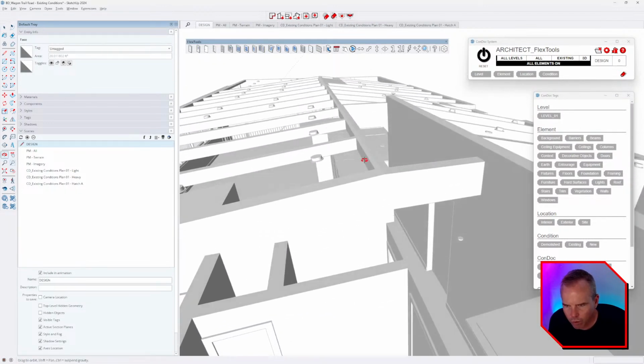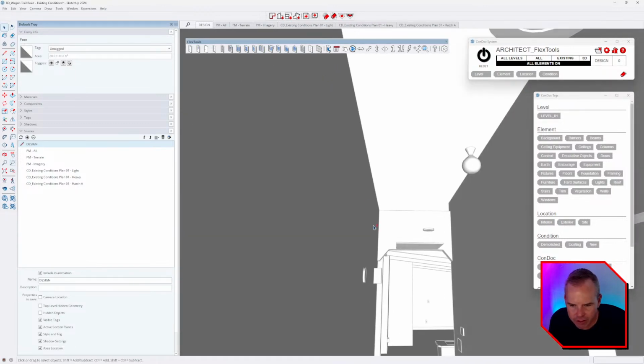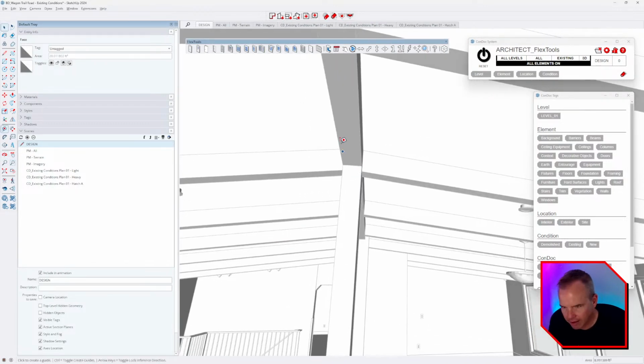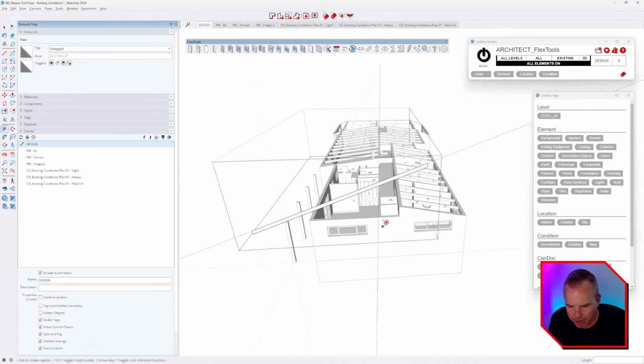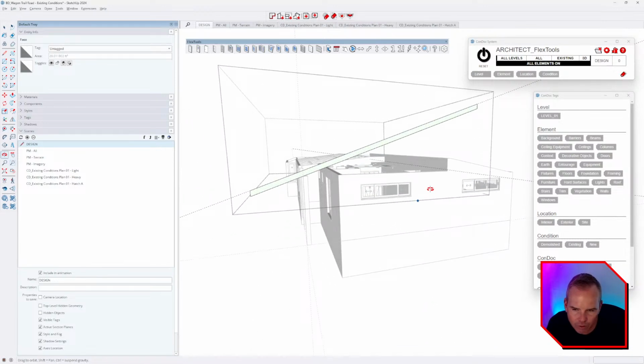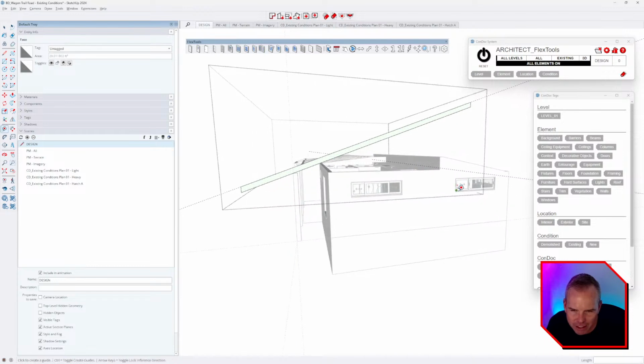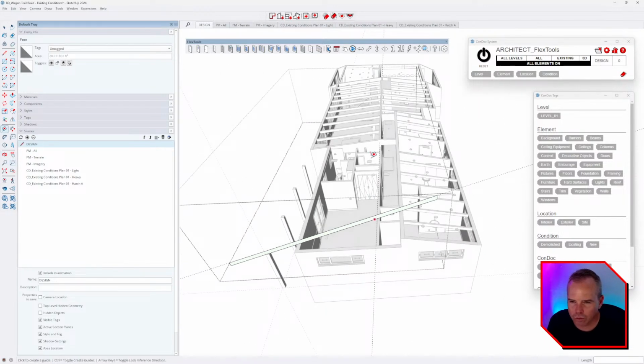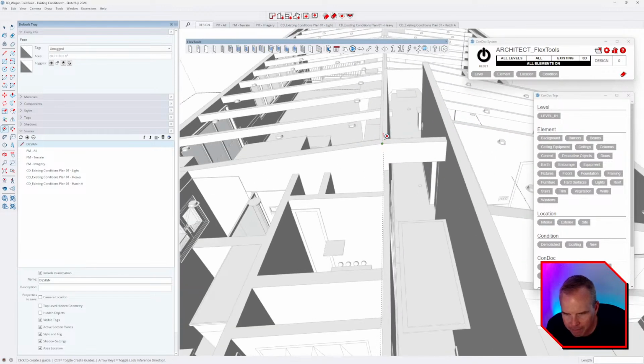So let's start with what Canvas came up with. Canvas came up with this center line, and I'm just going to throw it like this right there. So that's what Canvas came up with. And in hindsight, I'd probably just work off that. The reason I knew to go look for that is because the structural engineer made a comment about my drawings and said, hey, just a heads up, your center line is right on top of this. He went back out and did some field verification, and I had this center line perhaps just a few inches over.